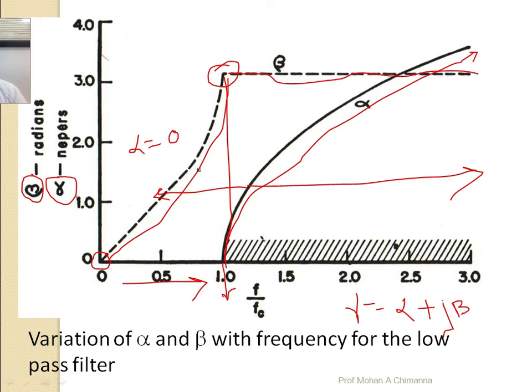While the frequencies are transmitted from input to output side, the phase constant beta is unstable and still keeps increasing as the frequency increases. But just before the cutoff frequency, your phase constant comes to a stabilized position, indicated at a constant level.